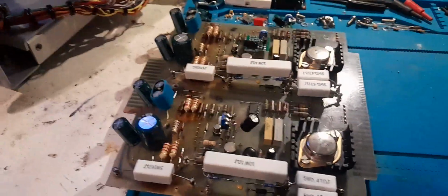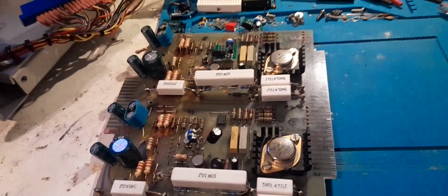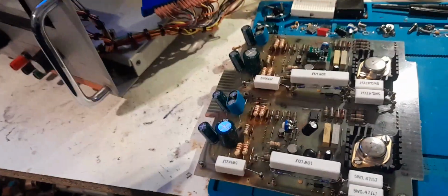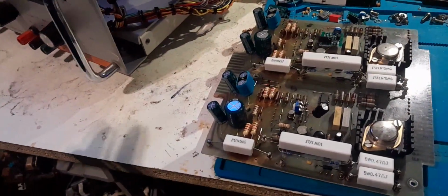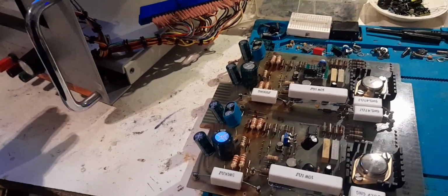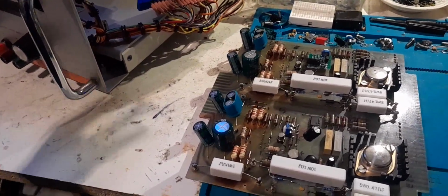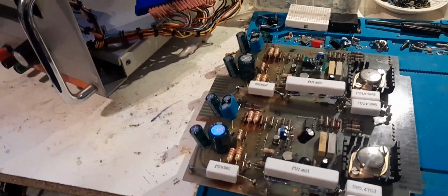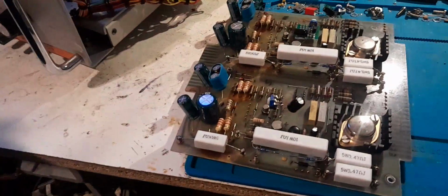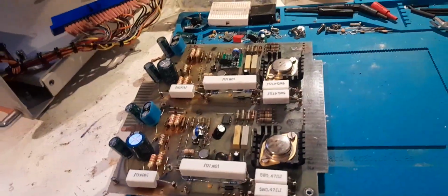You know, something else I just noticed, which is a bit concerning, because the entire time I've had this thing, I've always wondered if someone's done something, because there's solder on one of these lugs here. Like I said, it's just a bit strange how when you change the two constant current pots, in one you can put a 5k in there and it still works, the other one you put a 5k in there and the voltage changes. Both sides are supposed to be the same. I don't get that. That's within independent mode. That's what really throws me.